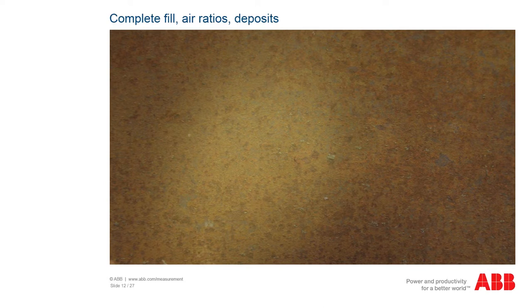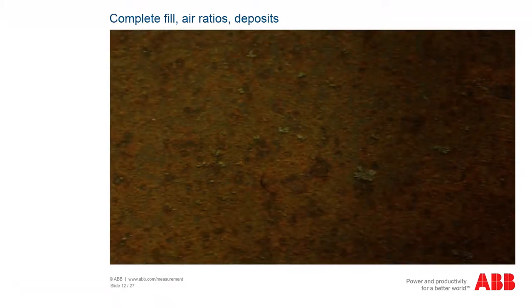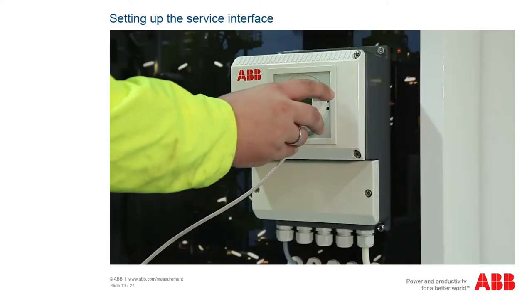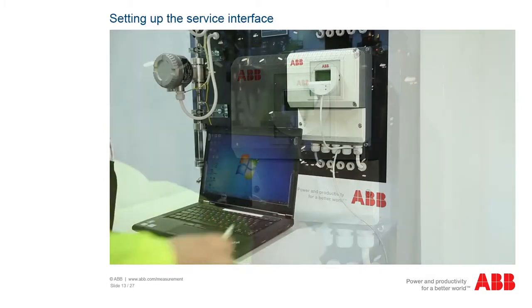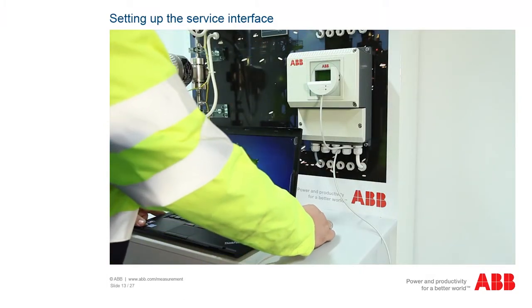An insulating deposit also leads to an incorrect measurement. Here, however, a higher flow is indicated. Therefore, it is recommended that after a certain time and in the event of an unanticipated deviation in the measured values, the device and the electrodes be cleaned. If the electrodes are excessively dirty or cleaning no longer appears to be useful, the sensor or the measuring unit should be replaced.